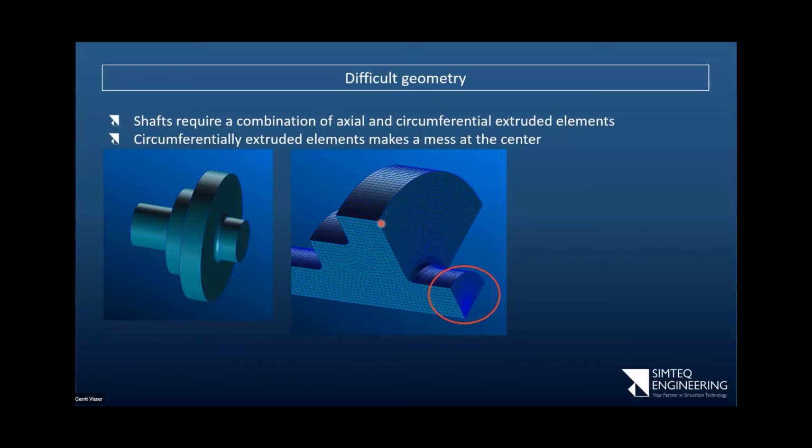So what's already obvious there is that the element outside may be close to perfect aspect ratio, but as you move in the other two directions, it's about the same size, but in that direction, the theta direction, in other words, the circumferential direction, the element starts getting smaller and smaller until, if I zoom in there, these elements are really, really horrible. So it's large in this direction and a fraction of a millimeter in that direction. Okay, so this is a bad way to model things.